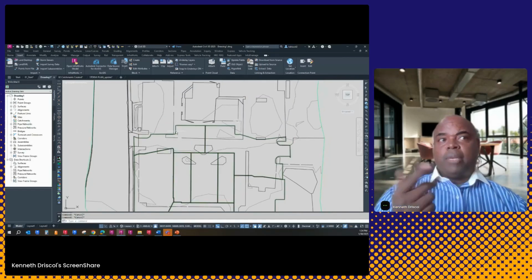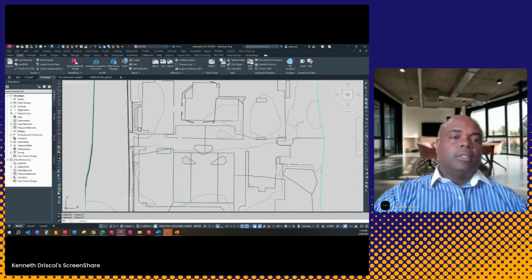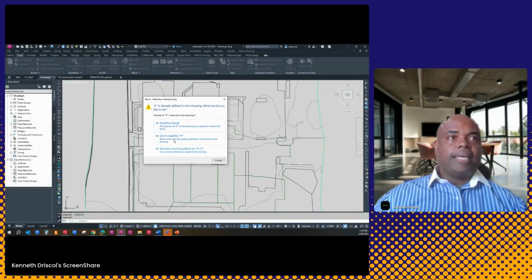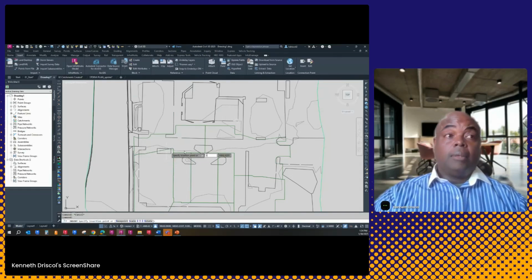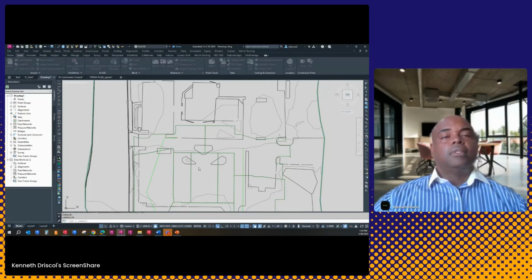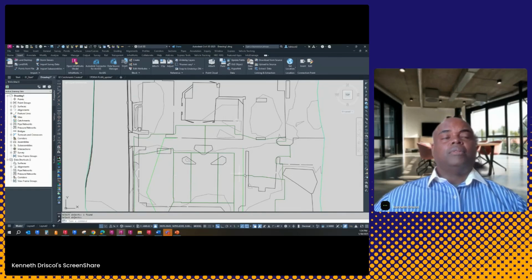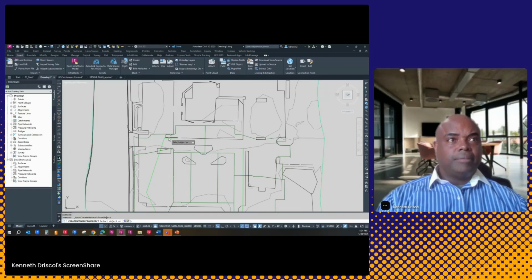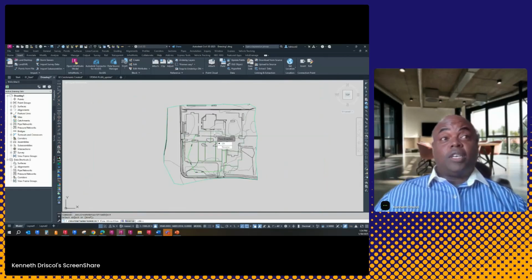even a pipe network. So to make that work, I'm going to bring in just a polyline. And I'm not going to redefine it. So I'll select 0,0. So here's my polyline. And I'm going to explode it just to make it simple. And from this, I'm going to create a pipe network based upon my polyline. I'll pick it. It shows the flow going, which is where I want it to go.